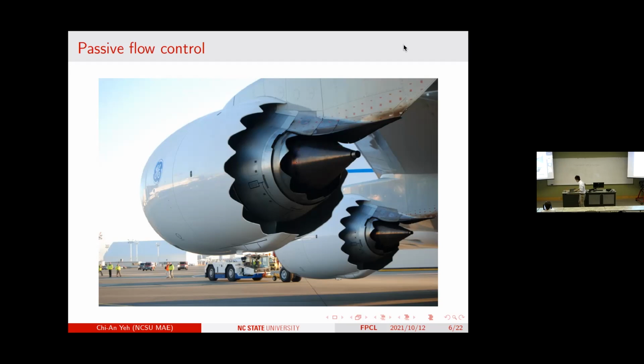You want the vortex ring to form, but when it's forming, you introduce a circumferential instability wave so that by the time it forms, it already carries that circumferential or azimuthal wave structure. That gets amplified while propagating downstream, and eventually it dissipates into streamwise vortices.